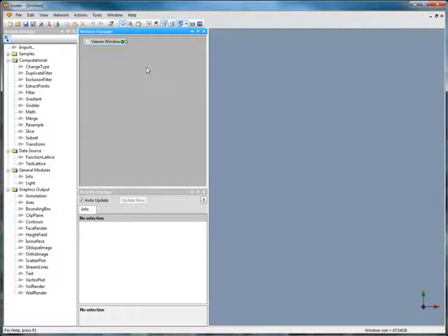Well renders are based on well data that is imported with azimuth, dip, and measured depth, directional survey information, or pre-computed X, Y, and Z values positioned along the well path. Axes, bounding boxes, and clip planes can be created from many different types of input, including data files, grid files, lattice files, or from other graphics output modules. I will create an example of each graphics output type.